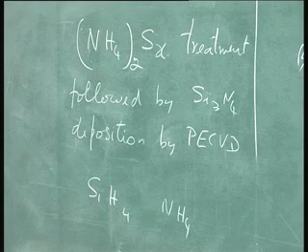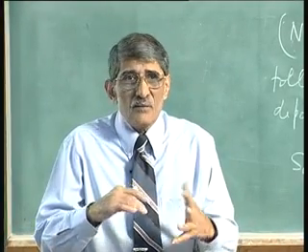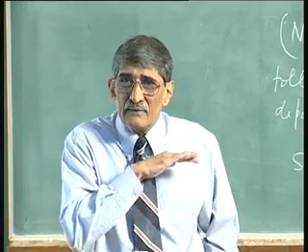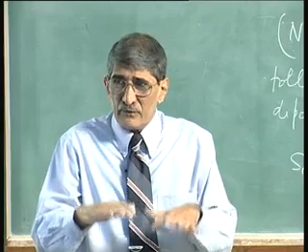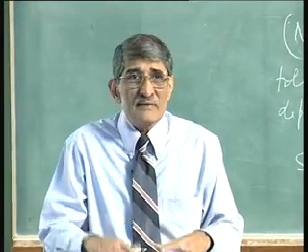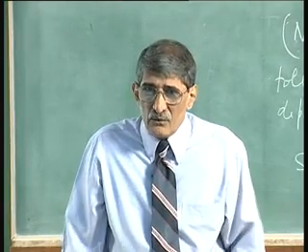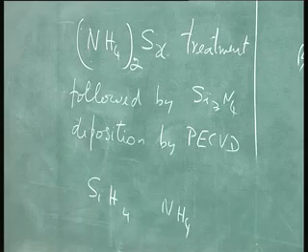So, now the ammonium sulphide does the job of removing the oxide, exposing fresh surface and passivating the layer. The PECVD nitride put on the top does the job of protecting it from further coming into contact with the outside world. So, when you make devices, in fact, these devices have been fabricated using epitaxial layers.